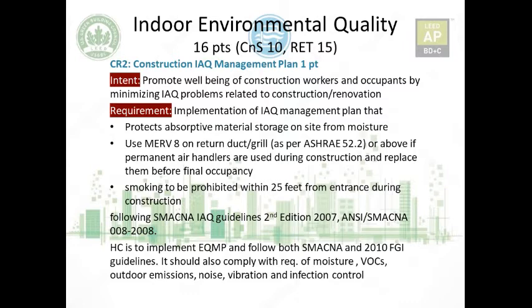And similarly, the smoking we have just seen: not only after construction or once the building is occupied, even before, during construction, it should be prohibited within 25 feet from the entrance. And the IAQ management plan should also follow SMACNA indoor air quality guidelines, second edition 2007, and American National Standards Institute and SMACNA 008-2008. I know it gets boring when you have to reference so many standards. SMACNA is Sheet Metal and Air Conditioning Contractors National Association. I'll give you a brief introduction of what it deals with.